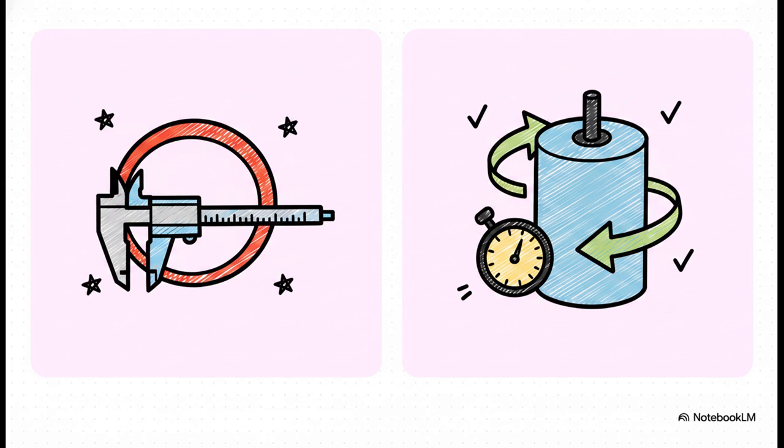You could totally have a part that is perfectly circular, but its center might be completely offset from the rest of the part. Circular runout, however, controls that form relative to a specific functional datum axis. It asks, is this shape a perfect circle, and does it rotate perfectly around our chosen functional axis without wobbling? You use circularity when you only care about the shape itself, but you mandate runout when that shape actually has to spin around a specific centerline.